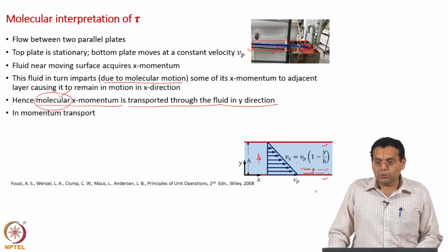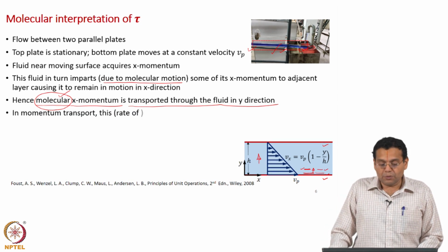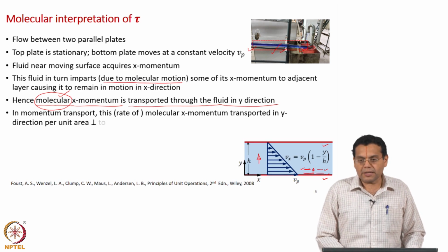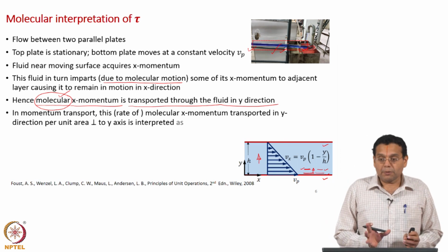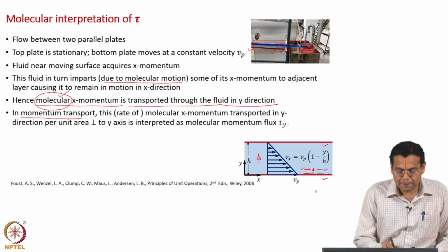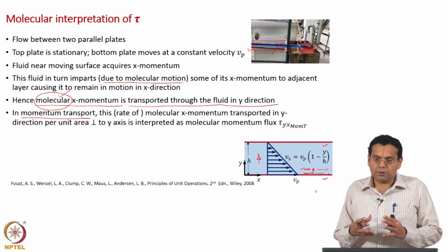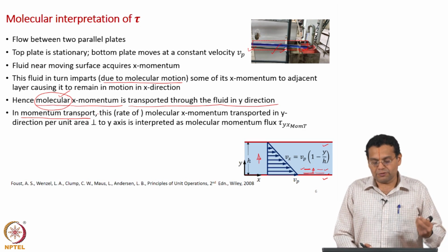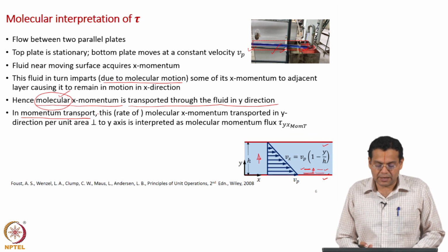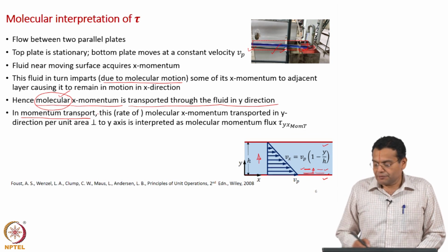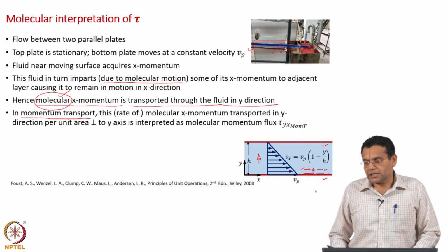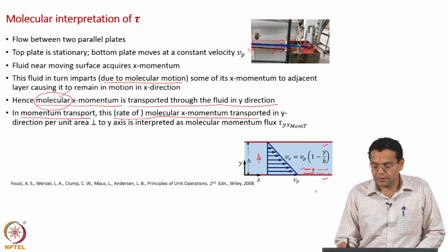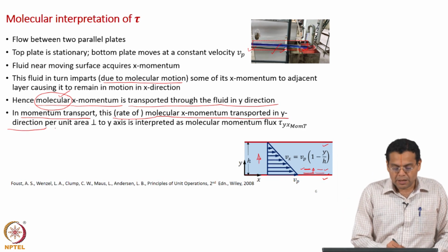Okay. Now, how do we interpret tau? How do we relate this tau to the momentum transported? In the momentum transport approach of analyzing fluid flow, as opposed to the fluid mechanics way of analyzing fluid flow, we have talked about the transport of x momentum in the y direction, the rate of molecular x momentum transport in the y direction per unit area.